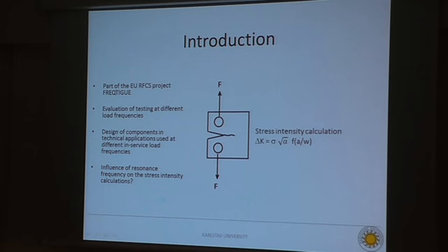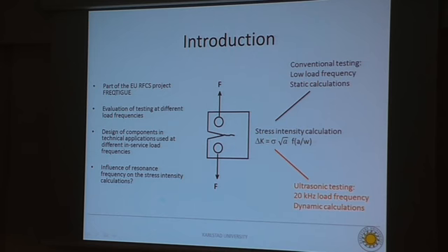One question that we are trying to answer with this paper is if there is any influence of the resonance frequency on the stress intensity calculations. Conventional testing with low load frequency usually requires only static calculations of the stress intensity. But when we are doing ultrasonic fatigue testing with 20 kHz load frequencies, then we believe that dynamic calculations are required. And what we are doing here is both static and dynamic calculations, for comparison and to see how the difference looks.